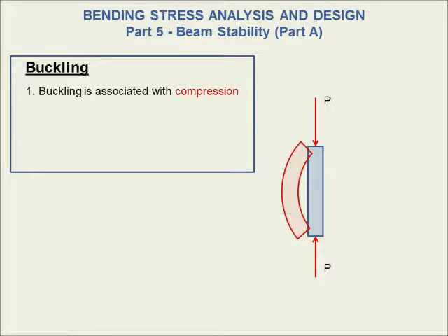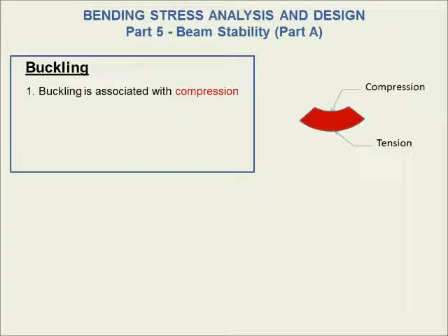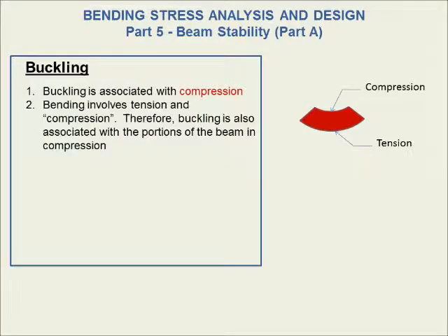So how come we're talking about a compression phenomenon when we're talking about bending? But if you recall, bending has to do with compression and tension. Therefore, buckling is associated with the portions of the beam in compression. So if you have a beam in positive bending, it's making the smiley face as we can see here on our red diagram.